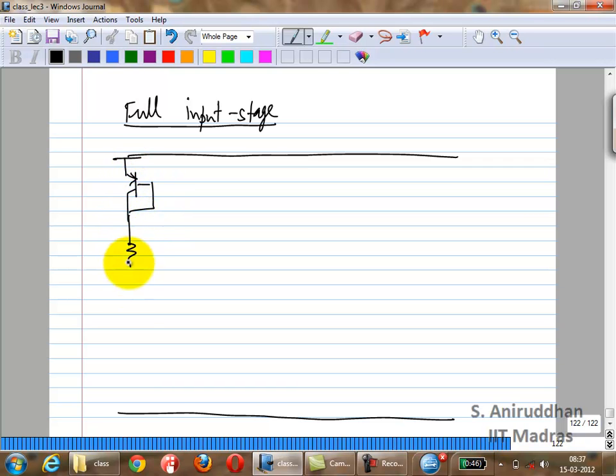So first I'm going to generate this. I'll call this R5, which is 39 kilo ohms. Okay, so what you'll see is even the values of the resistors and so on are fairly standardized for this 741. Then what changes from product to product? It's typically the betas of the transistors, the speeds, things like that. Those will depend on the process.